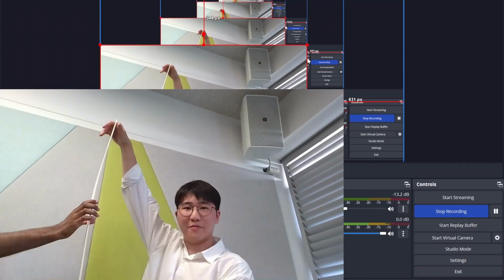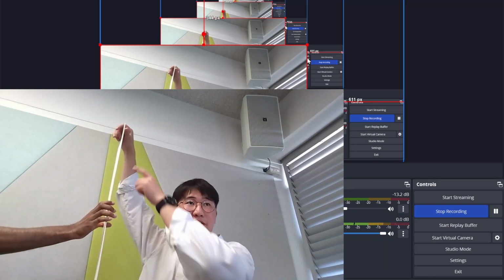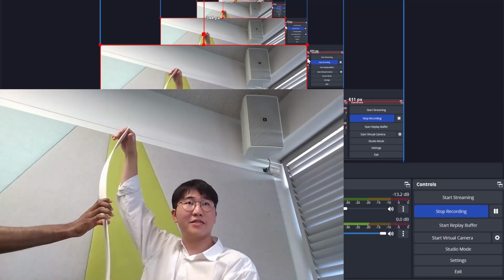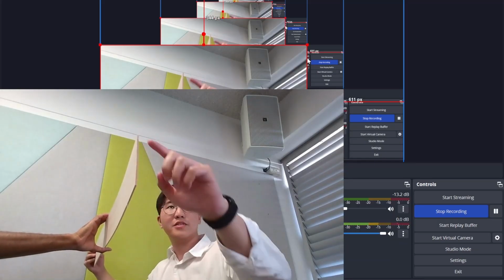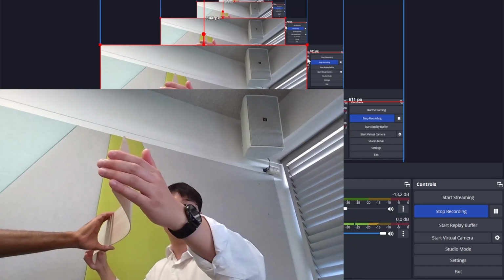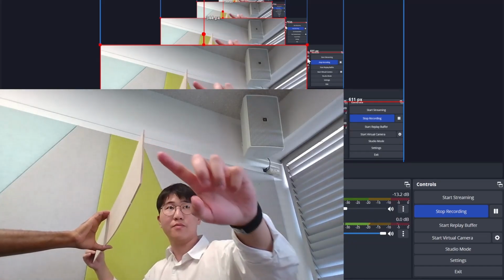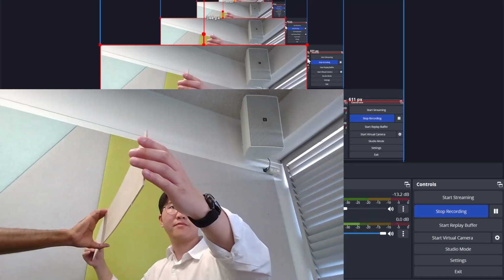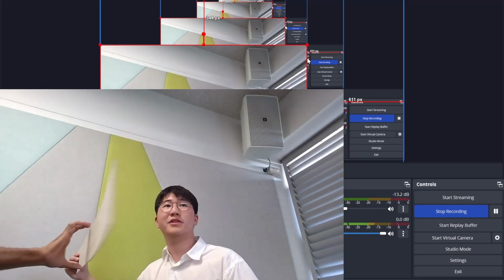Okay. Do you see how it bends in an S shape now? Yeah. So basically, we've halved the effective length in the minor axis direction. But because this is so different in terms of the depth versus the breadth, it's still going to bend in the minor axis direction. But if they were more similar, so if this was more rectangular, more like a block, then you kind of have to compare which one's going to fail first, the minor axis or major axis bending.